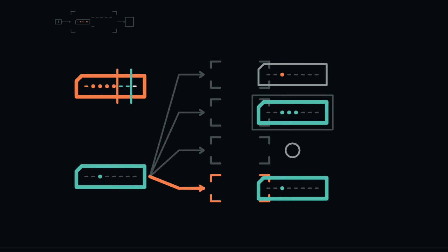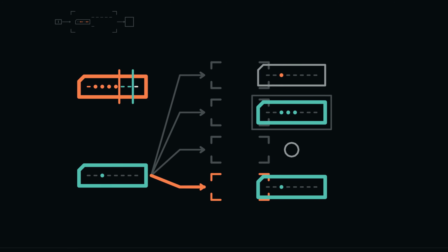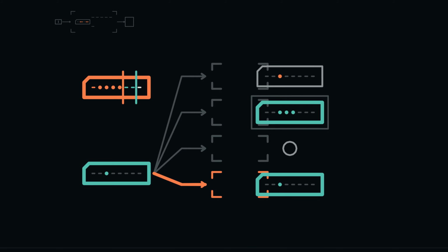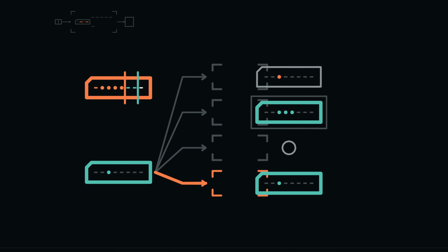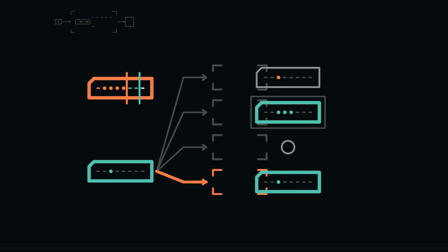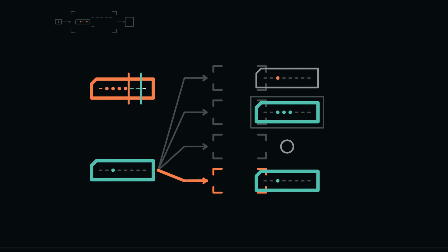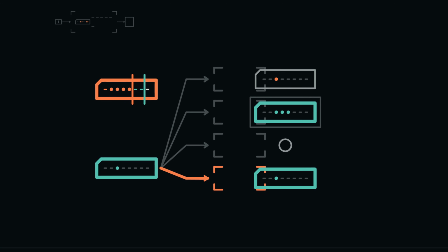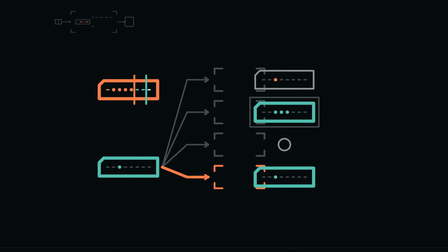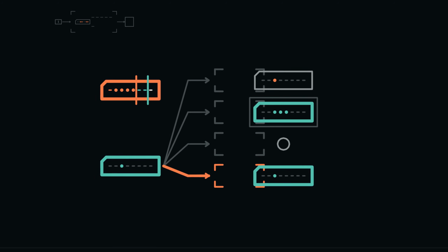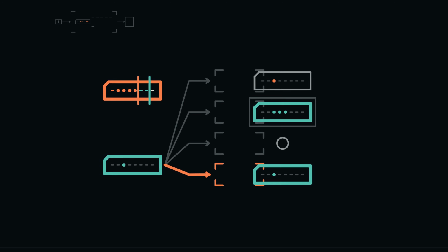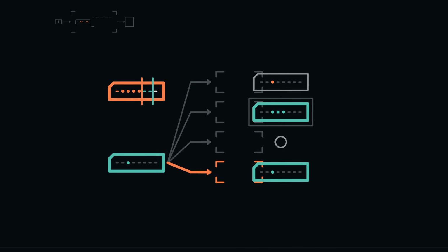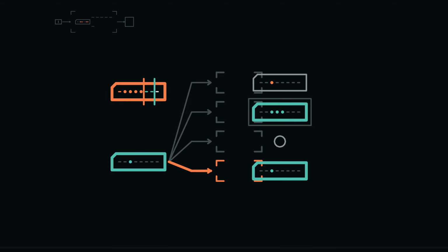Control flow instructions use the fields more narrowly. Hexadecimal 78 followed by 20 decodes as branch if 0, target 20. Opcode 15 selects branch if 0. A must be 0, I must be 0, and B is the even target address. If the 0 flag is set, execution replaces PC with 20. If 0 is clear, execution preserves the PC that already advanced during fetch. An odd target is illegal because every instruction begins at an even address. The branch byte does not contain a looping action. It specifies one conditional next address choice.